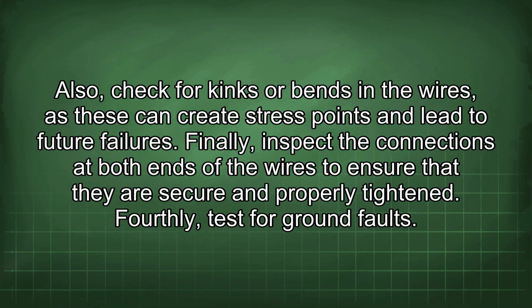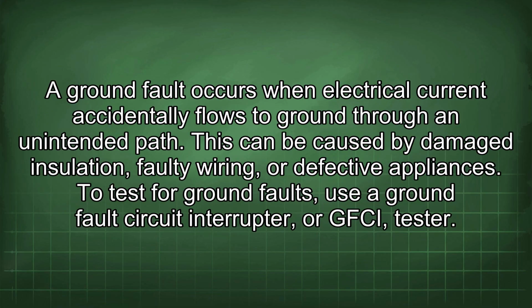Fourthly, test for ground faults. A ground fault occurs when electrical current accidentally flows to ground through an unintended path. This can be caused by damaged insulation, faulty wiring, or defective appliances. To test for ground faults, use a ground fault circuit interrupter or GFCI tester.